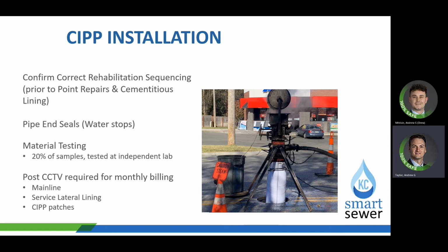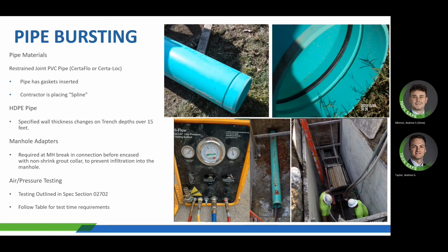Also, within CIPP lining, make sure that the contractor is submitting their post-CCT review before the monthly billing. This is for mainline CIPP, as well as service lateral lining and CIPP patches. Another item is pipe bursting. This is very popular these days compared to the old open trench excavation method.